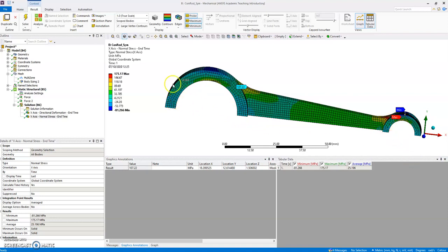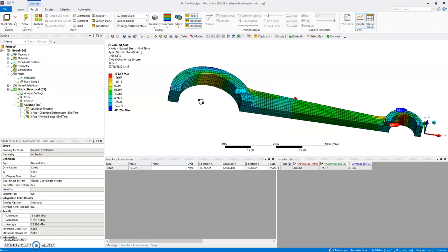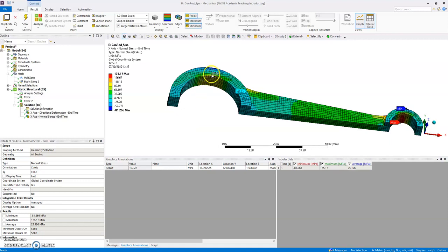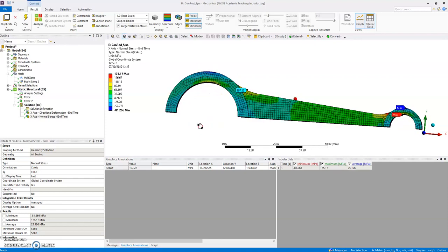All the force will be pushed on these. And the way a force boundary condition in ANSYS is applied is each element has an area, and each will have applied a proportion of the 1.25 kilonewton I had applied. So there are some loads here as well, but that's not what would happen in a real case.